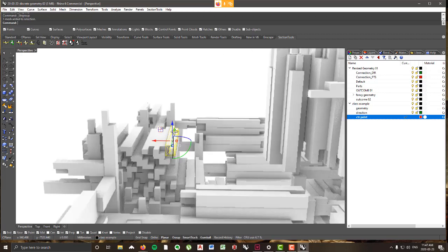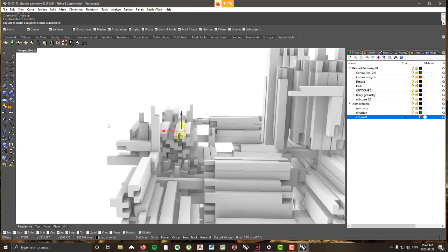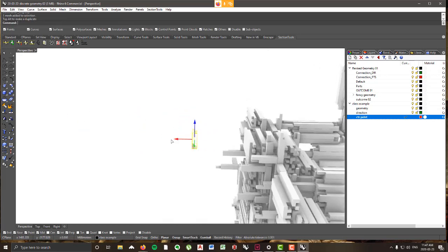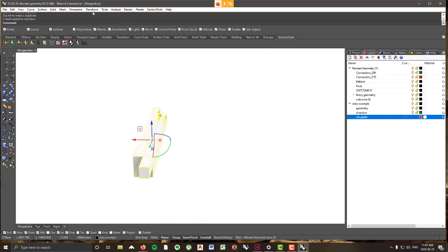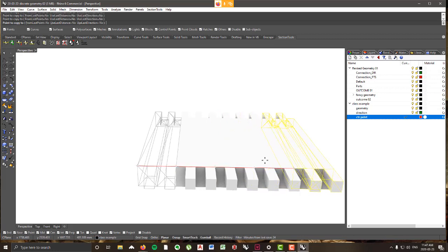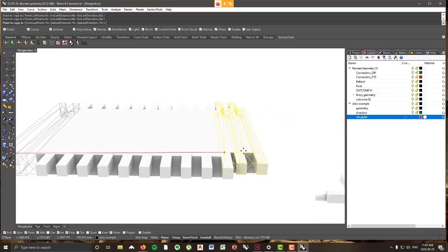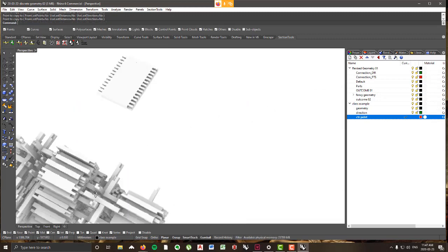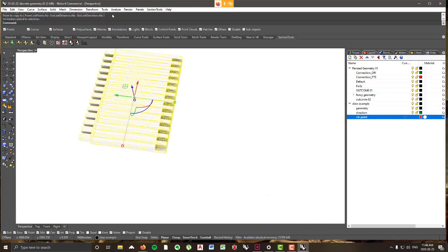So for instance, I selected maybe one component here, and I went transform copy, made sure my vertex select was on, and I just kind of copied this over, right? So now let's double this up, copy. And I just started to say, okay, this is my floor module. So I kind of faked it. And I mean, honestly, this is good enough. So I said, this is my floor module.